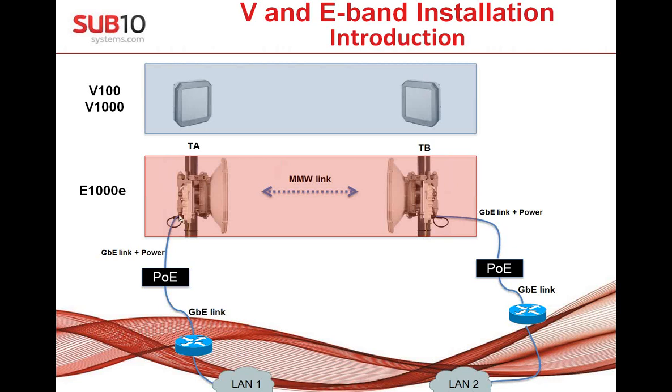But the specification for gigabit Ethernet is 100 meters. You cannot create a standard gigabit Ethernet connection longer than 100 meters. But now, if you are setting up the link, keep in mind that PoE is not active data equipment. It's just a power injector. It's passive equipment.